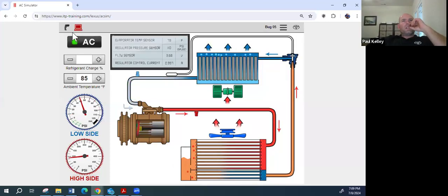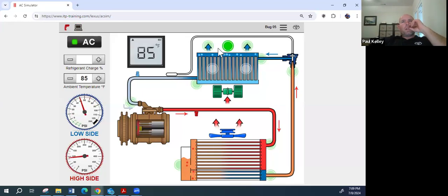Alrighty, we turn the AC on, we hit it with the temperature gun, and hey, it's 85 outside, and it's blowing at 81, 85, 85. This is essentially blowing at ambient. Wait a minute, look at what these are doing something here, aren't they? These are like oscillating back and forth. But the compressor clutch is pumping.